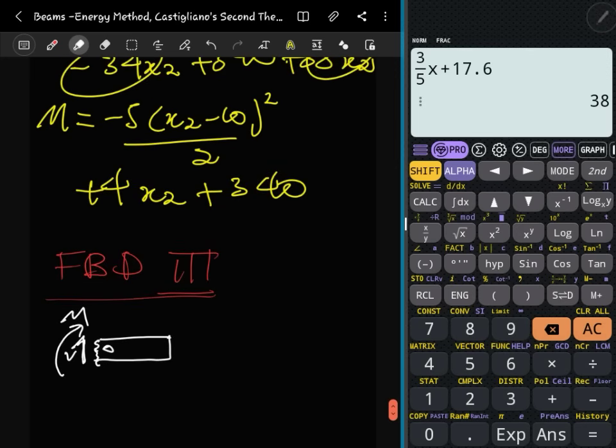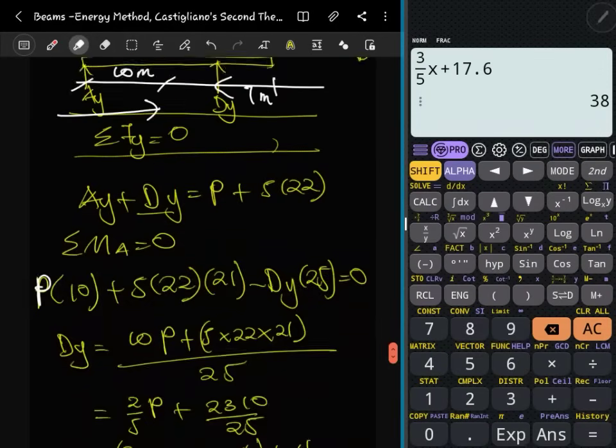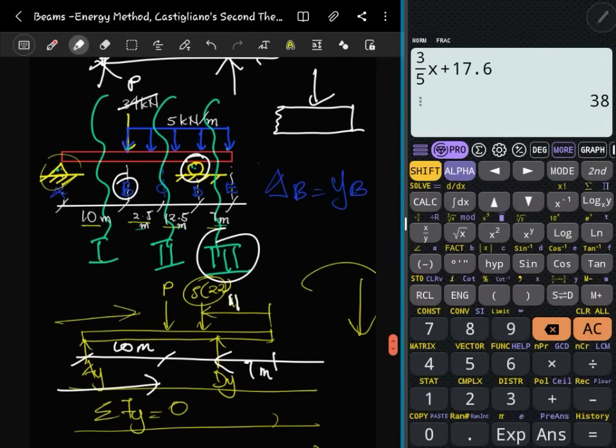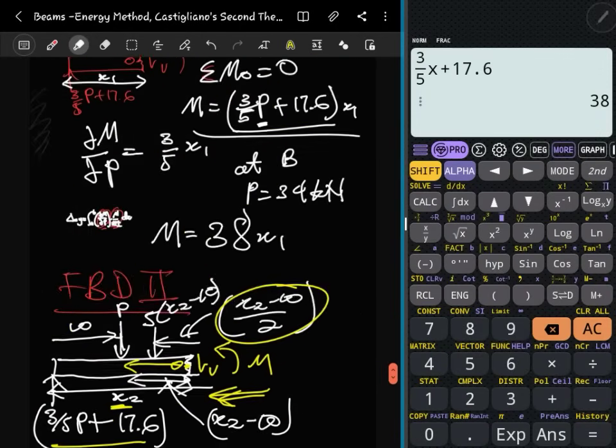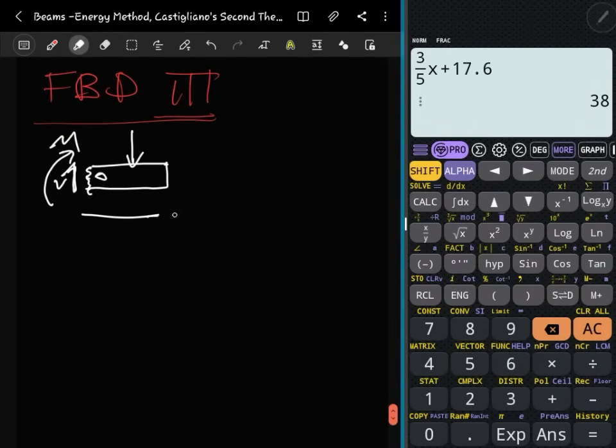And then here, the only force that we're encountering is the uniform distributed load, only the uniform distributed load. Let's go over it to confirm. Yeah, only the uniform distributed load, and it's actually acting on the entire thing. There's the third section. The whole length is x3, and we know the load here to be 5, acting on x3. And the distance here is x3 on 2.